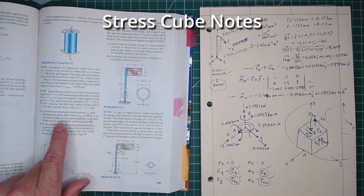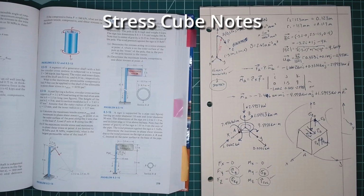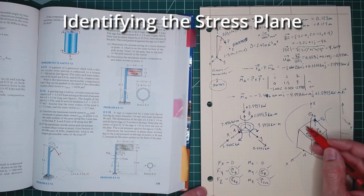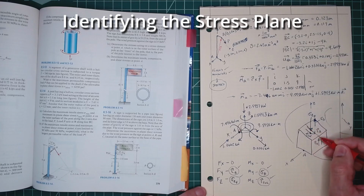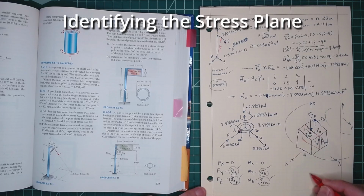Now they talk about in-plane shear, the maximum in-plane shear stress here. So how are we going to calculate this? Well, this is a three-dimensional stress cube, and we want to go to a two-dimensional stress plane. Essentially, the shear stress is acting in this plane, kind of the YZ plane. So what we're going to do is take this cube and split it like this, and that is going to become our stress square.